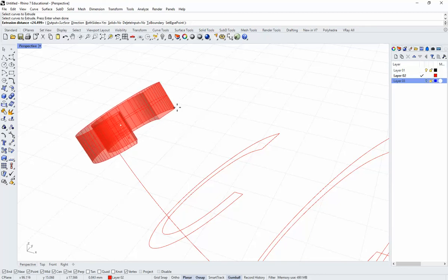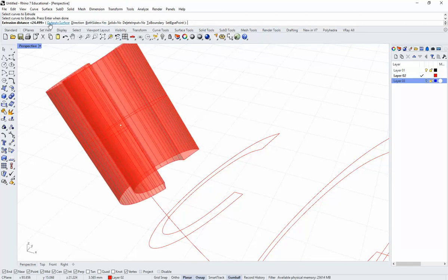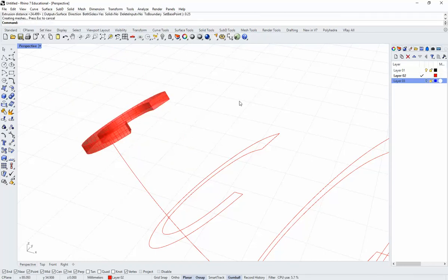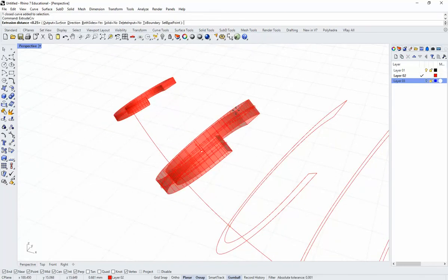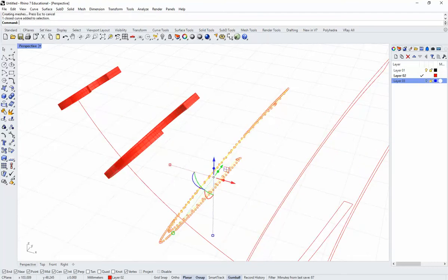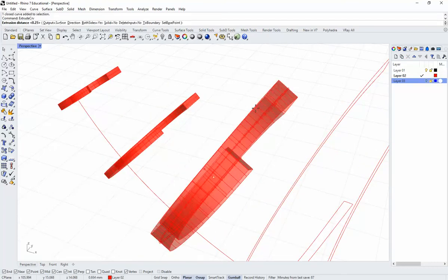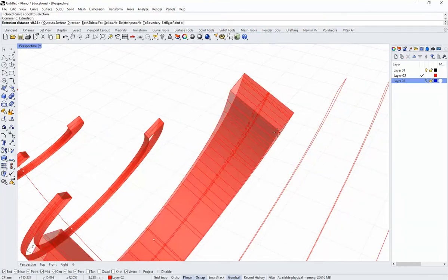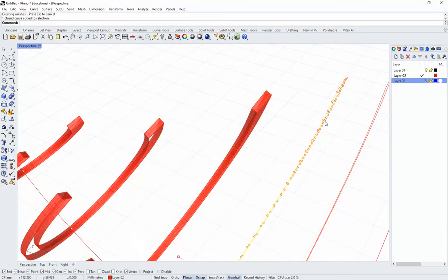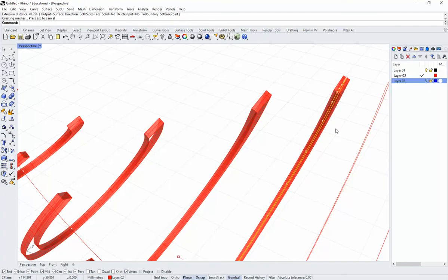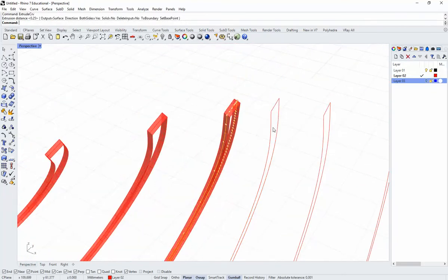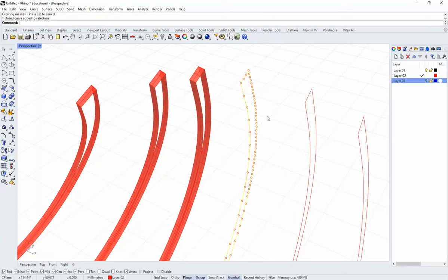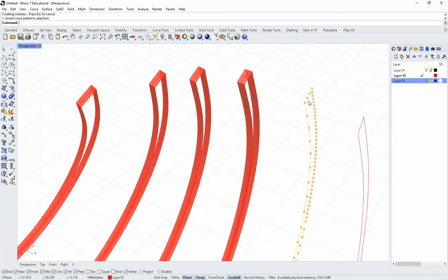And this works for planar curves only. Both sides, yes. The extrusion distance, once again, will be 0.25 in my case. And then I'm going to just do this one at a time. If you don't do it one at a time, it won't know which direction to select, basically, because these are in different directions, right? Remember, they're non-parallel. And all I'm doing is just reselecting a new curve, running the command again, hitting enter, because it'll repeat the same data that you put into it before.